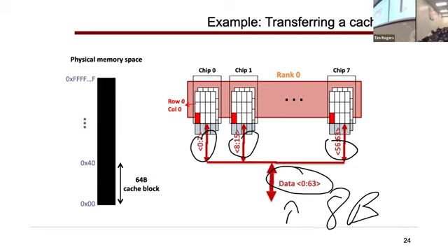Okay, so your memory system is operating at some frequency. There's clock domains everywhere in modern circuits. Your core operates probably around 1 to 4 gigahertz. Memory systems tend to be slower depending on the memory technology, somewhere in the range of megahertz to low gigahertz range. And what that's talking about is the speed at which you can clock out data on this bus.